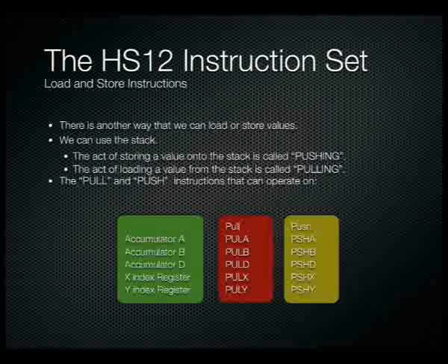If you want to put something on the stack, then we've got the equivalent push command. So we've got push A, push B, push D, push X, push Y, and they allow us to temporarily push the values onto the stack. They don't actually delete the value out of the register that we're pushing from. So in the case of doing a push A, we don't delete the value in accumulator A. It still stays in accumulator A, but we put a copy of that value onto the stack. And then later on, we can trash that value in accumulator A, override it, do some other processing with another data value, and then later on, when we need that value back in accumulator A, we can simply pull that value back off the stack using a pull A. So it's a good way of temporarily saving values that we might need later on.